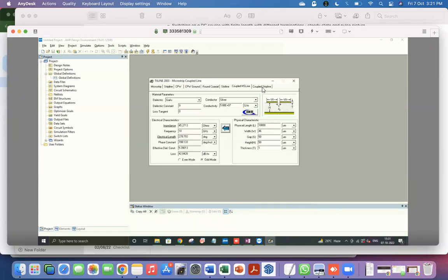So what that means is that the same physical length corresponds to different electrical lengths for the even and the odd mode, because the speed is different. And this creates a problem. And this is basically because the microstrip is not a true TEM mode, and there is this participation of air and dielectric in different combination. This does not happen, however, in the strip line version of the coupled system.